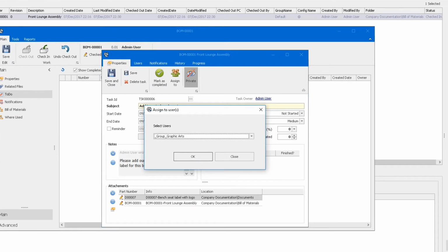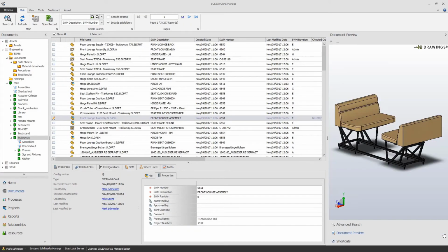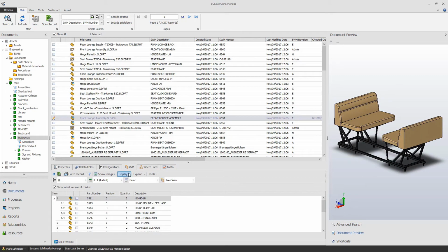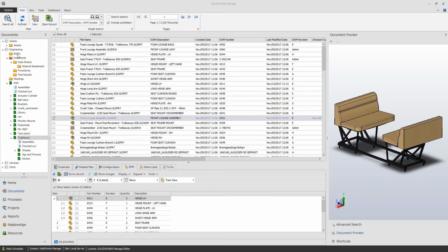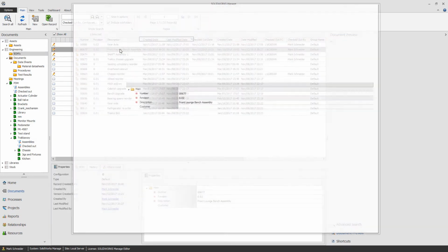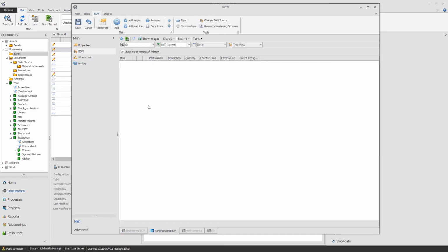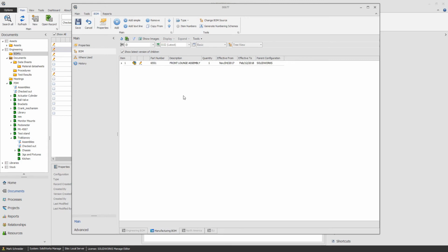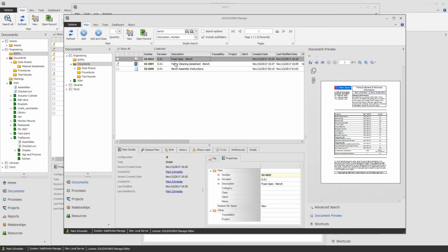We have been speaking about tasks. And how can we create different variants of the bill of material inside SOLIDWORKS Manage? So I have here a CAD model showing, let's say, a car seat. And within that design, I did not create the seat build. I did not create, as CAD, for example, jigs within that design. However, I need to drive the manufacturing bill of material, which is a different variant, according to the engineering BOM, while adding additional items to be useful for manufacturing people.